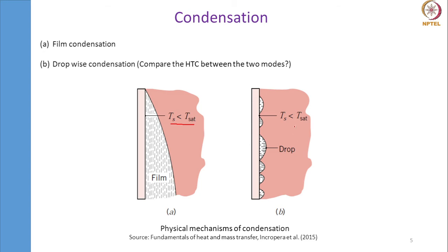Yeah, that's perfect. So the heat transfer coefficients in dropwise condensation are certainly one order higher than what we get in film condensation because, as we see in dropwise condensation, the surface is such that only a part of the surface is being blocked by the liquid condensate, whereas in film condensation, coalescence of different drops happens and then it forms into a layer.